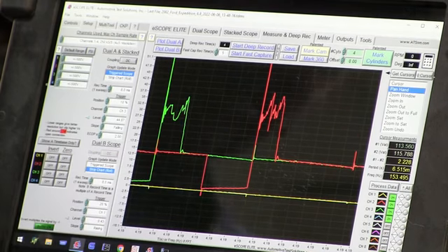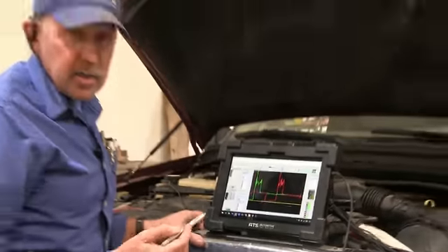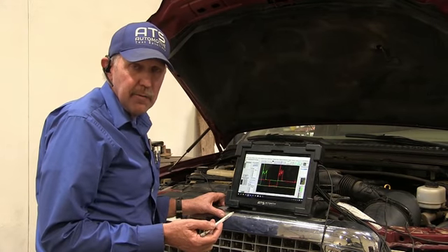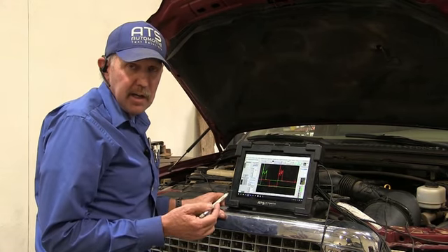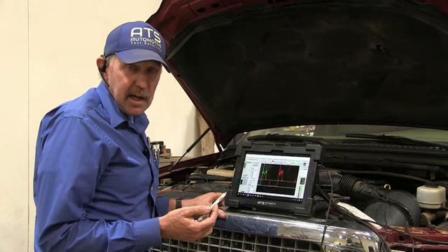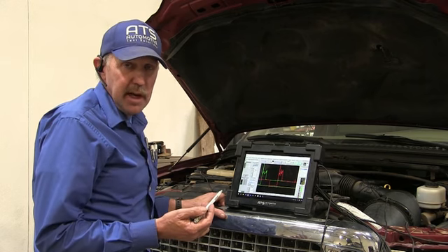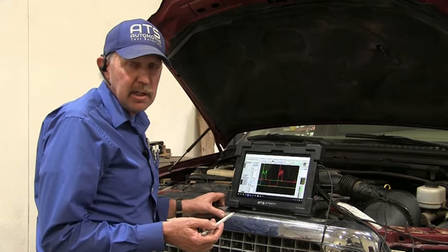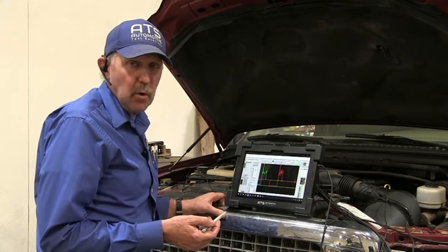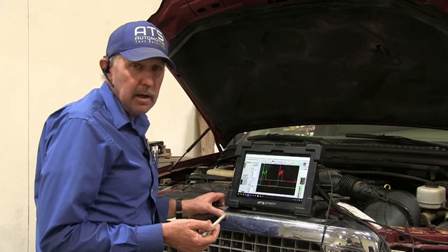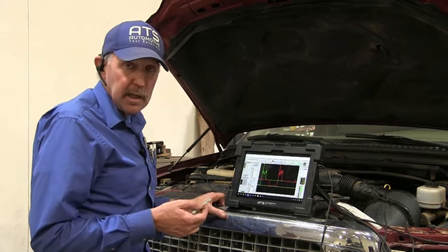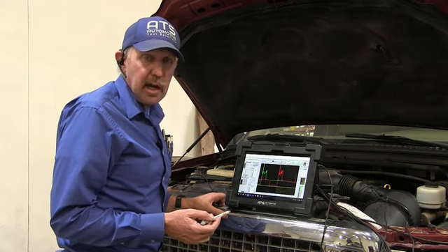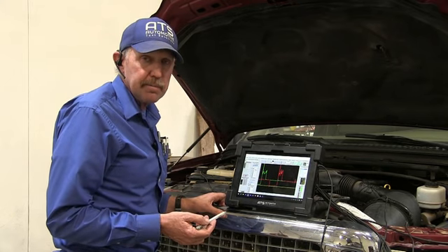So guys, this looks really good. This car has 200,000 miles on it. We only put 1 can of CRF, 505 CRF in here. And for a 200,000 mile engine, it might take a few cans. So what I want to do is add another can before we deliver it to the customer so it'll clean up a little bit more as the customer drives this vehicle. But I'm confident that I'm not going to get this car back right now. 9 looks just fine. 9 is okay, so I'm going to be okay with this.